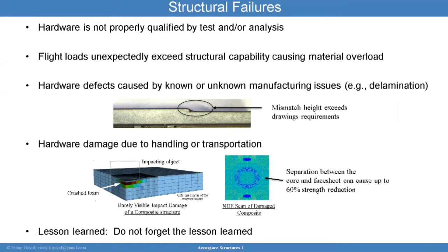And so as a consequence, your testing will have been done at lower load levels. And then when you go to flight, since the flight loads will be higher, potentially because it was not fully characterized, then there might be a problem. And you could have a failure by material overload, which I'll be discussing later today.